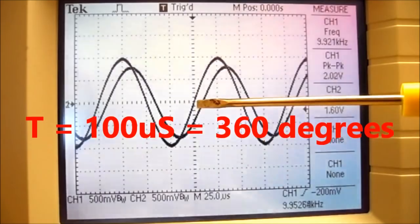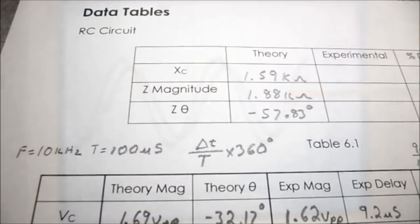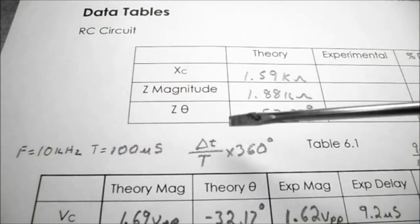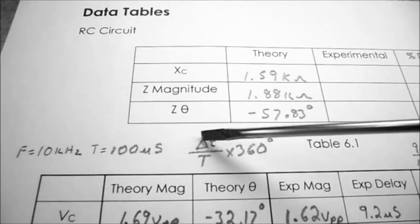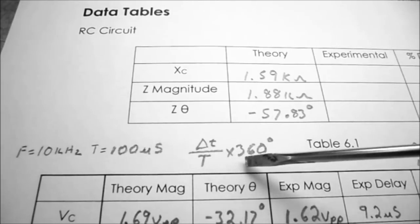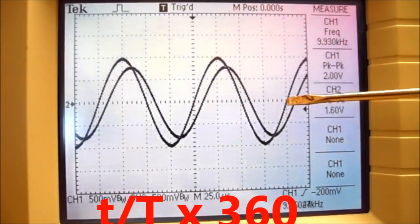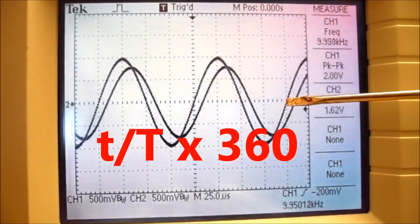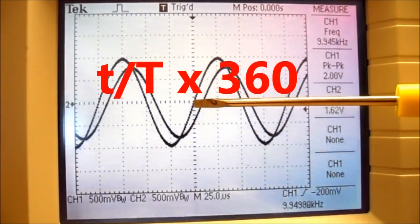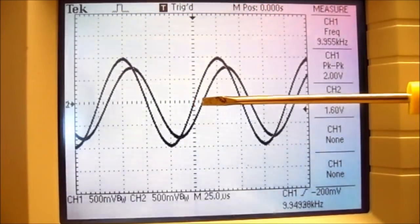So in order to do that, I know one complete waveform is 360 degrees. The formula we use to compute phase angle is delta t, or the change in time from one waveform to the other, divided by the period times 360 degrees. So if I take the change in time over the total period times 360 degrees, that will give me my phase angle here. Now in order to figure out what that is, I'm going to use the cursors.